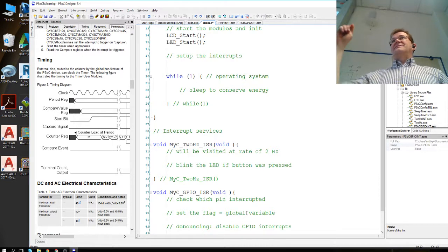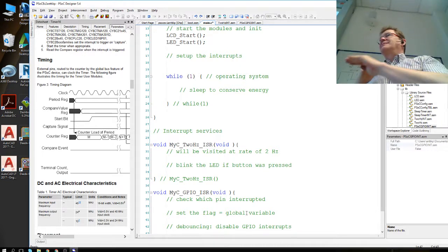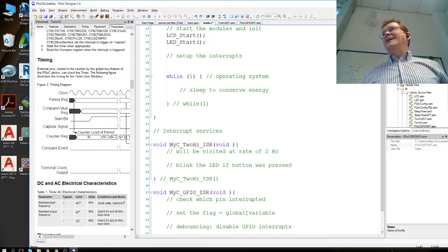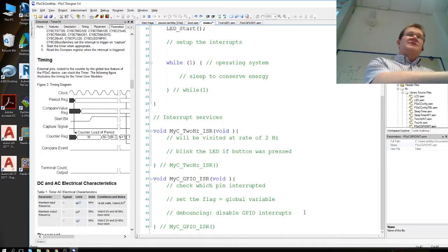So basically, it would mean that we would do nothing here if the flag is on. Or use the same flag, but there are different ways of doing it. But use one which works. This actually works quite nicely, since then it also saves a little bit of computing time, since it disables interrupts, so there's no overhead due to that bouncing.